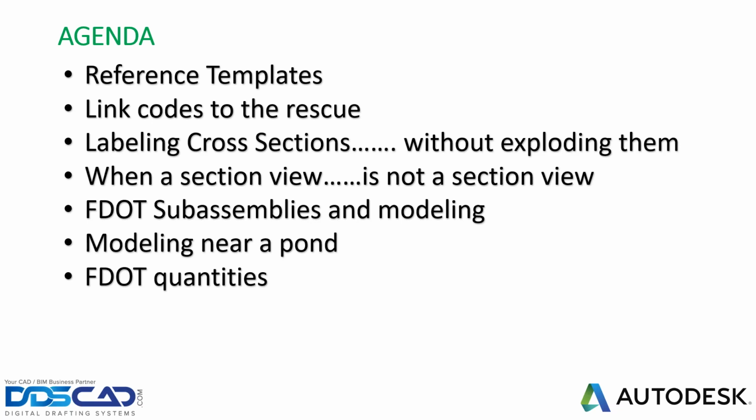Then I'll discuss the FDOT quantity tools. If you've seen quantities done in MicroStation, in Civil 3D now we have the full gamut of tools. In fact, I just completed a project where I did this completely in Civil 3D. I found a couple of little bugs that I submitted to the DOT, and they're going to fix them with the next release. It didn't take me that long, and I automated all my summary quantity sheets in Civil 3D. So that's now completely an option.